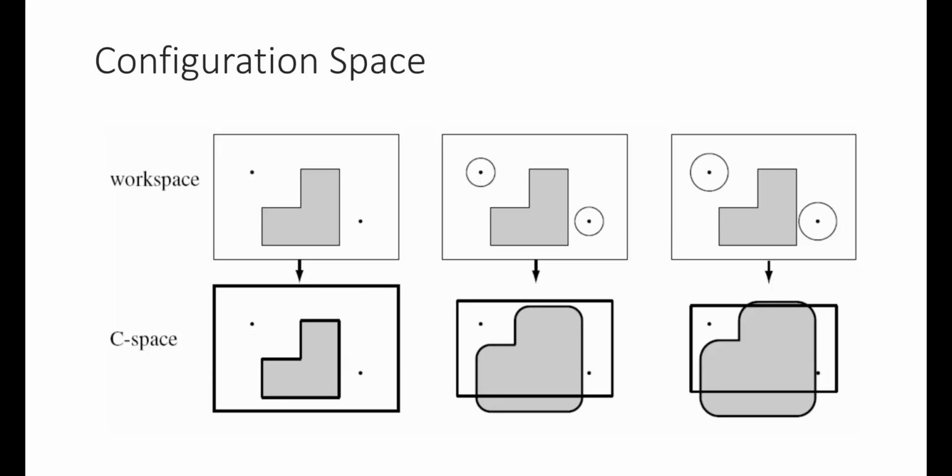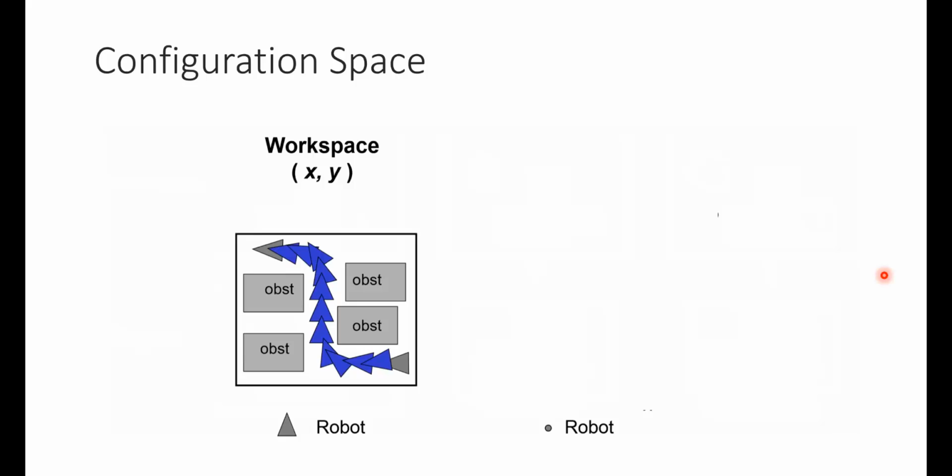What about if my robot is, say, non-holonomic, or let's say it's orientable, and so that means my robot can rotate around. So let's take this example. We'll go back to that triangular shaped robot. And so now in XY space, in my world space or task space here, I have this path of my robot. What is that going to look like in configuration space? So I have these obstacles. I have my X and my Y axis. What will my axes be in configuration space?